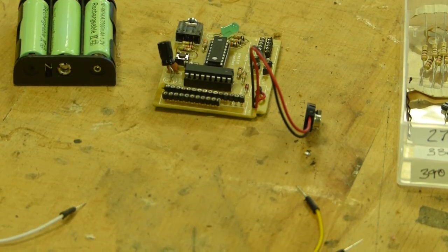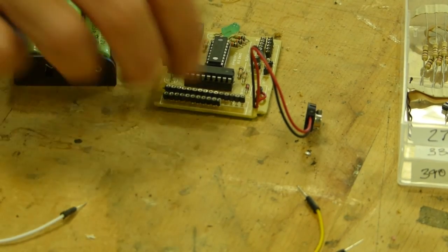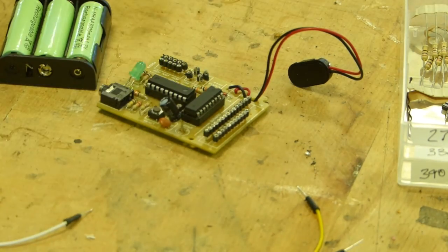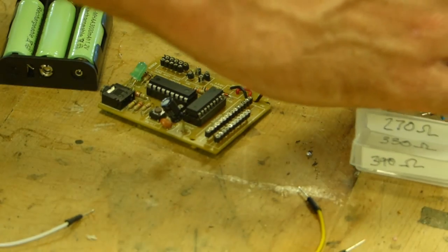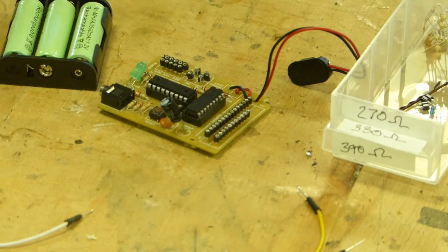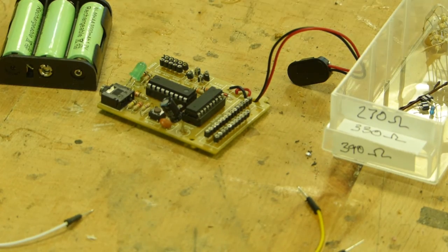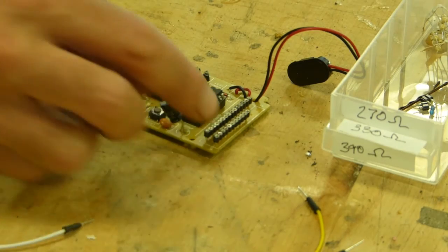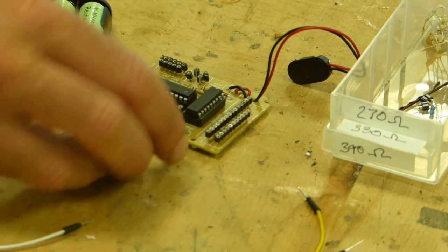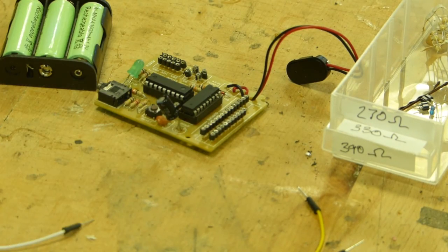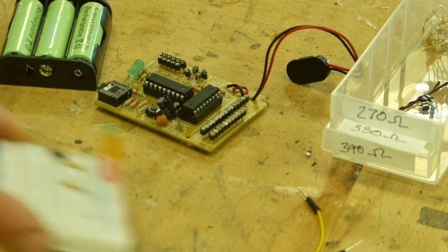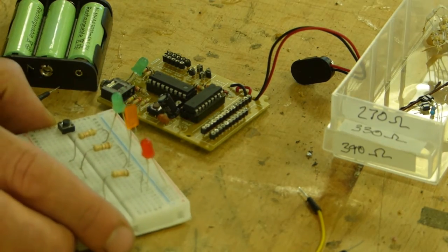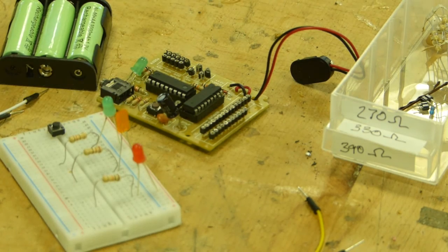So now I'm going to make this circuit in real life. Now we're going to plug LEDs into these outputs here. Because, remembering in the second video, we need to protect the LEDs with resistors to stop too much current going through them. We want to have something in series. Now it's not going to be so easy to plug an LED in series with a resistor and then back into another line like that. So we use what's called a breadboard here. In true Blue Peter fashion, here's one I made earlier. Now I'll plug this up and I'll show you how it works.